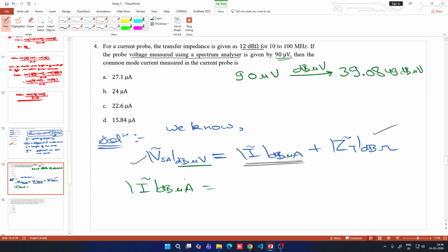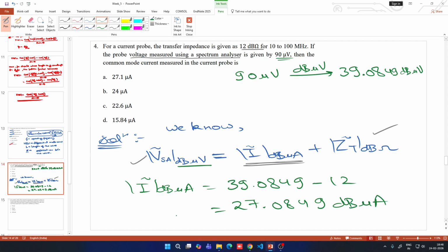Now I can directly substitute it here. So it will be 39.0849 minus 12. This is the transfer impedance in dB ohms, and when we solve this we will get 27.0849 dB microampere. And if you match it with the given option, the correct option here is...